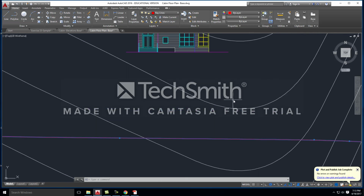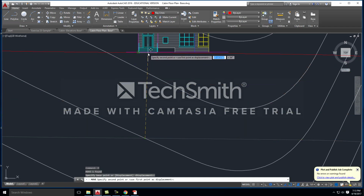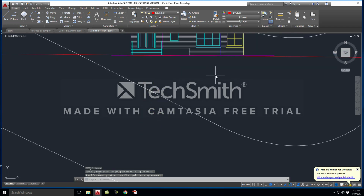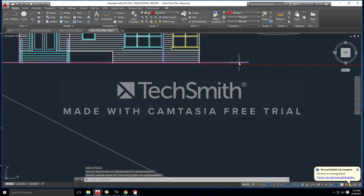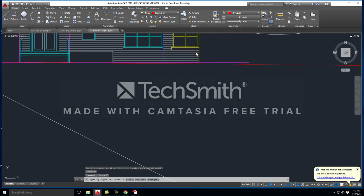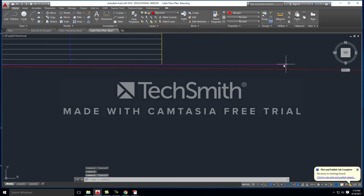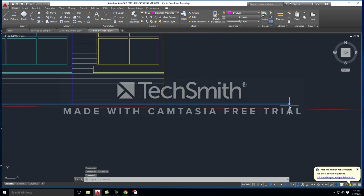Okay, so from there I can go ahead and move this up and line this up with our floor plan. Okay, so I'm going to line it straight up, connect it like so, and I can now get rid of my purple line. Okay, so this right here is currently a block. I'm going to go ahead and use the explode command to get rid of that. So notice our old elevation line is right here. So that was where we used to show where grade was. I'm going to go ahead and delete that.